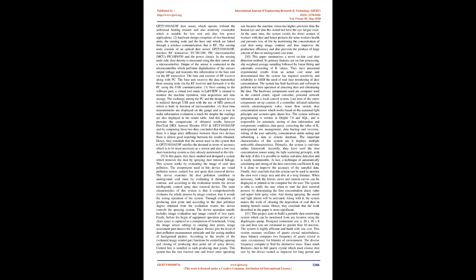The Arduino is associated with the dust sensor through a circuit, and it is also associated with the Raspberry Pi by means of USB. The Raspberry Pi then sends fine dust concentration information to the Android mobile application. Here the general operating sequence of the system is described in 3 steps. 1. Gather fine dust concentration raw information from the fine dust sensor. 2. Replace the information with processed information in Arduino and store the information in the Raspberry Pi. 3. Transmit the fine dust information through the network connection when an Android application requests fine dust data from the Raspberry Pi.